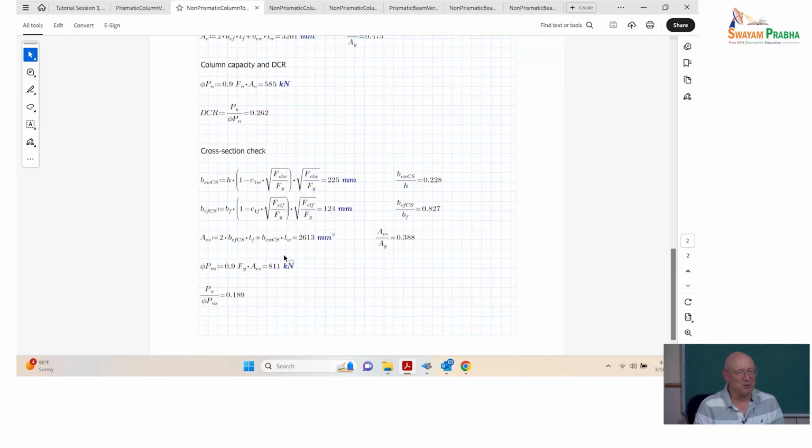That's how it usually works, but this problem does some crazy things because of the wild effective width reductions. So that file's almost identical to the one we did for prismatic, but the only thing we changed was, we're checking the top, and we went in with 12 instead of 11.97 for the eigenvalue.